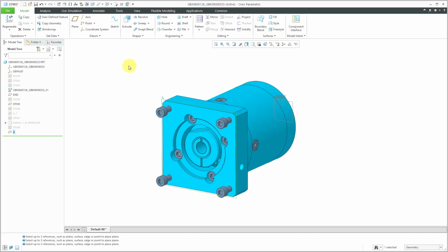So back in the day, after you created a datum plane, or you could select a datum plane, if you hold down the right mouse button, you can go to Properties, and here in the Properties dialog box, this button allows us to change it to be displayed as a set datum for geometric dimensioning and tolerancing. But this is the old 1994 standard. There was a new standard that came out in 2009 in which datum feature symbols should be associated with actual geometry, not these imaginary references like a datum plane.